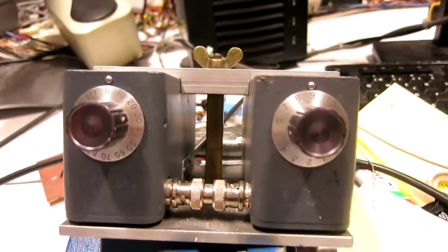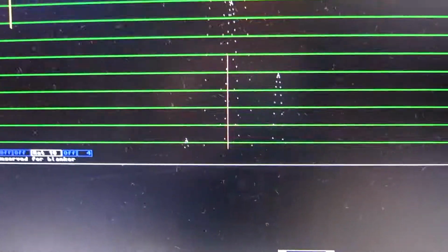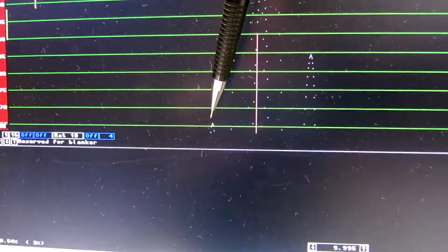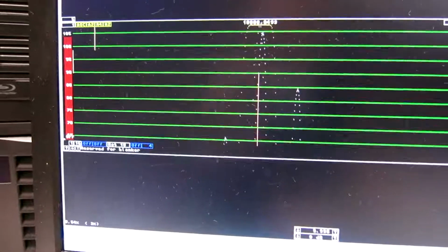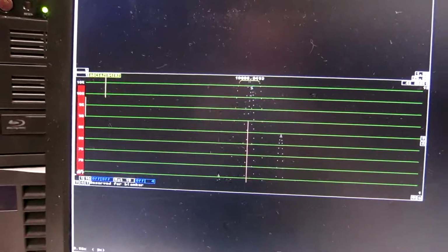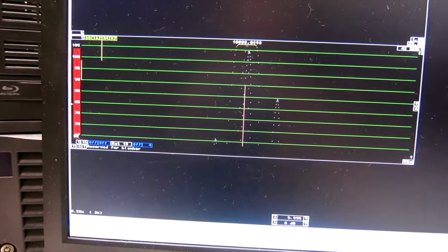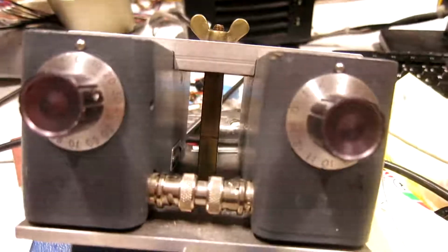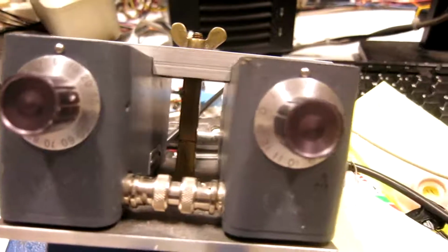At 9 dB attenuation, I start to see intermodulation in the crystal. The main signal 10 Hz up and a false signal 10 Hz down. I guess the temperature goes up and down with the beat frequency 10 Hz, and that affects the properties of the crystal. Now the attenuation is 3 dB and the crystal starts to behave irregularly.